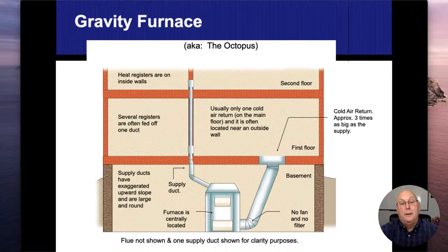All right. The fire would burn, heat up. It would get that cast iron refractory pot super hot. The circulation air would be on the outside. And as I mentioned earlier, we don't have a blower fan on these, so it worked on the principle of convection with hot air normally rising. So the hot air would start to rise.